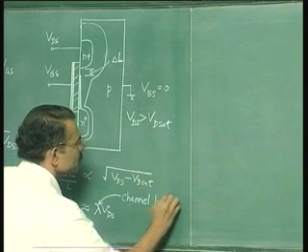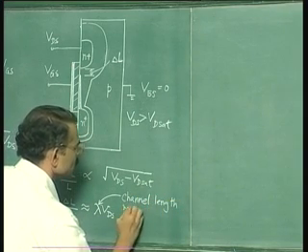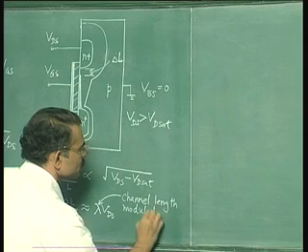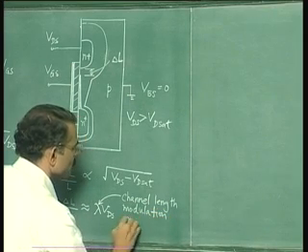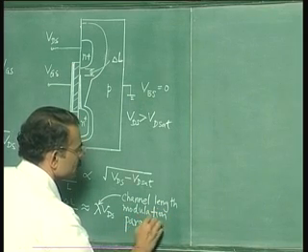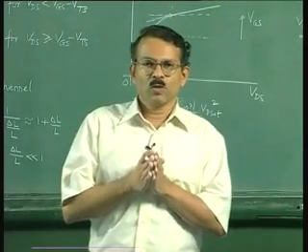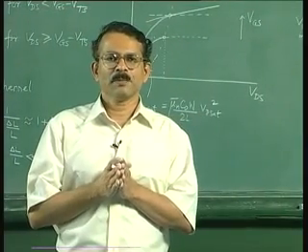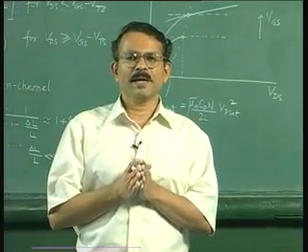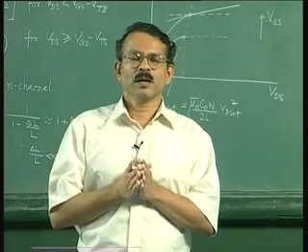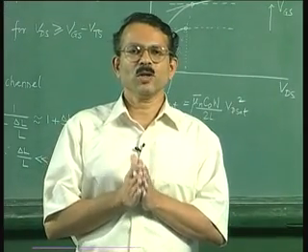Channel length modulation parameter. Now after doing this, what we do is we include that lambda VDS term also in the expression below saturation.